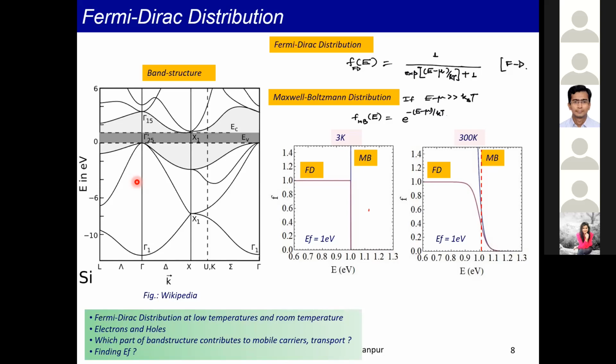Once you have the band structure, you can know about its electronic properties, magnetic properties, all those kinds of things. Now, a band diagram is something you use when you are making a device out of that material, where there is a spatial variation versus position. In a band structure, you are varying as a function of K of the electron. In a band diagram, we are looking at energy versus position. This is E versus K, that is E versus X. When you are making these heterostructures, then you usually look at those E versus X curves.